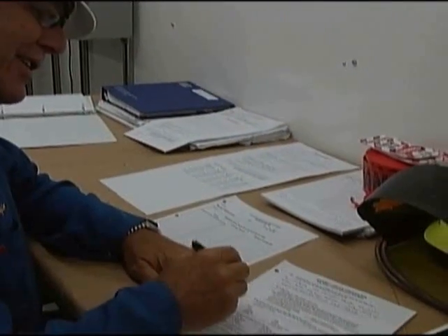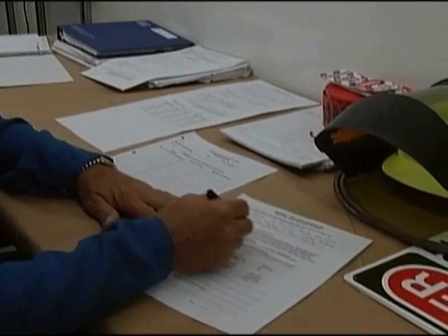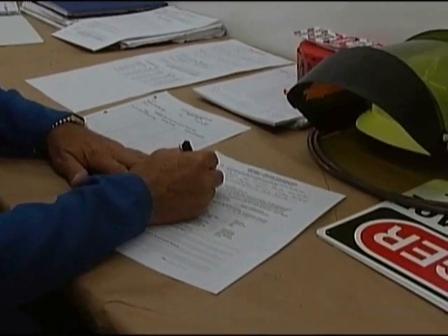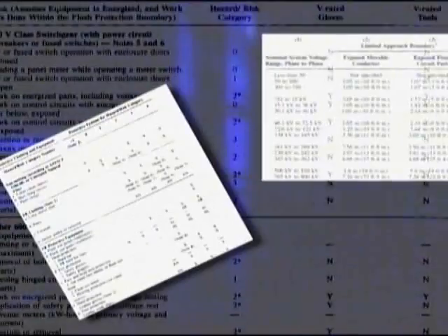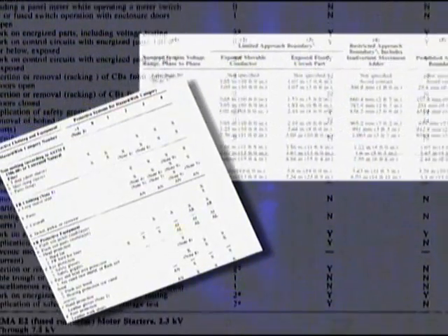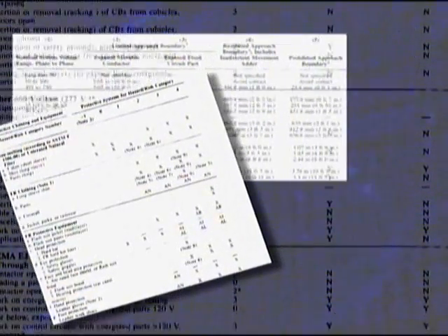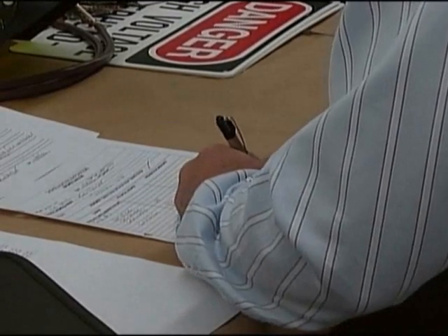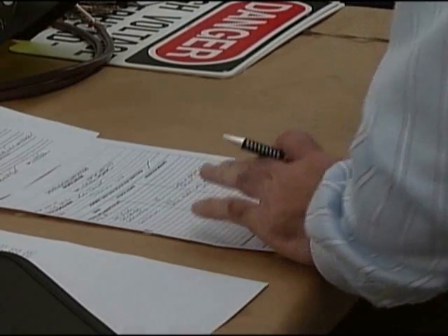Before performing any work, conduct a written hazard analysis of the area and the work you will perform. Refer to the proper charts to determine what level you will be working under and the appropriate equipment. Fill out appropriate work permits and other paperwork that is required prior to performing any work. Refer to the chart to make voltage and PPE determinations.